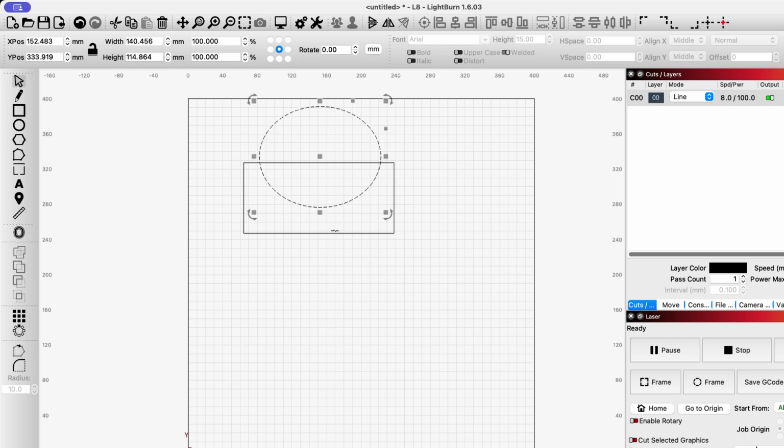There's a couple ways you can do this. You can use the Boolean tool. You can also use the cut tool. Let's see if this will work. No. Sometimes it doesn't work, so that's why you have to try the other tool. If we do our Boolean, see, that's the combine.